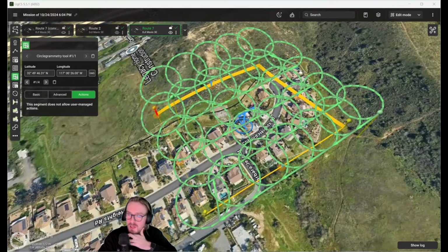Can I show how to process data after flying until exporting to the point cloud? Actually, in this case, I didn't do any. I know some of you do maybe some raw image processing, but in this case I didn't get that much into that. I just got the JPEG files. They were already geotagged since they came from the DJI Mavic 3 Enterprise. We flew with RTK GPS enabled there, of course. And then I simply put all the pictures in Agisoft Metashape and went through the standard process of processing that data.